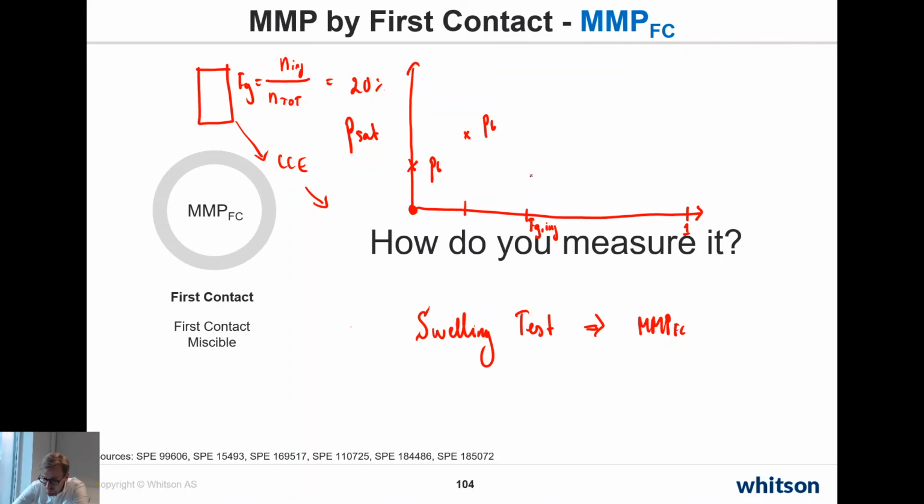And then we might do that for 0.4. Maybe it's still a bubble point right here. Then we do it for 0.7, and we see that the curve is starting to flatten out, and now we're actually measuring a dew point right here. Then we know that the critical point is somewhere between these two lines.